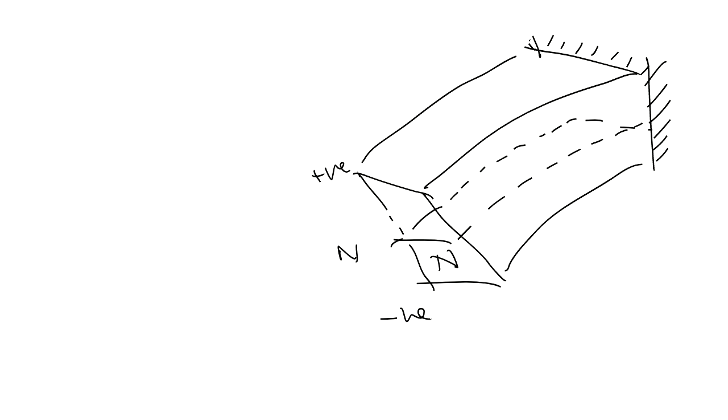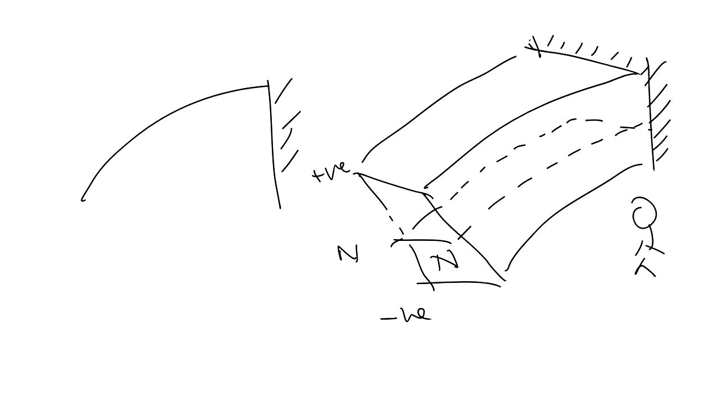Okay, so now I'm going to get back to the side, to the front view again. Here is the beam again, or cantilever. Here is the rotated plane. Here is your neutral axis, and here is the way you should draw your stress distribution. As you know, guys, the biggest tension stress is at the upper layer.